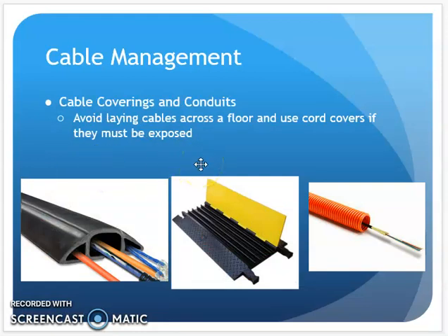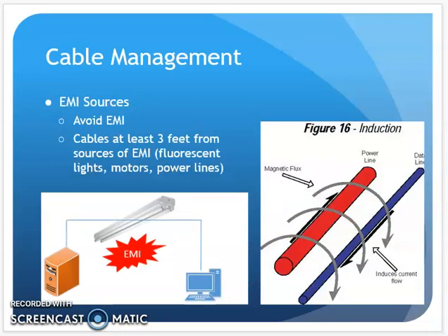I shouldn't really be laying cables across the floor. If I have to, for some reason, I should get them in some kind of protection. They make all kinds of channels that I can lay my cabling in to protect them. Up in my cable trays, if I have things like fiber optic, I might even install a duct up there. This is called interduct, to protect my fiber optic. So I'm usually thinking about protecting my cabling. I shouldn't be laying it on the floor, but if I have to, make sure there's some sort of protection over it. And things like fiber optic, I might even install in a conduit, even up in a cable tray.